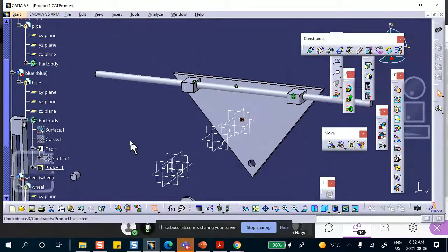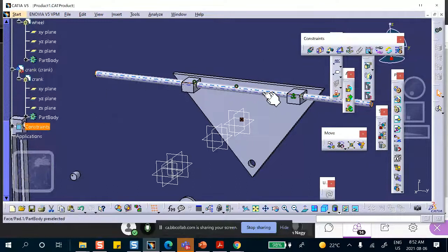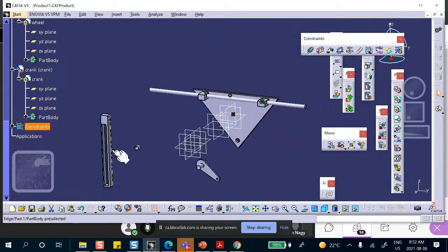Now, as far as that blue piece attached to the pipe, there's two ways you can go. One is you can use this paper clip and basically attach that to the pipe as a paper clip, which means it becomes essentially a single part and later becomes a rigid joint. That's one way of doing it. Let me go that route. Let me do it like that. So let me bring first of all this and put it on the pipe.